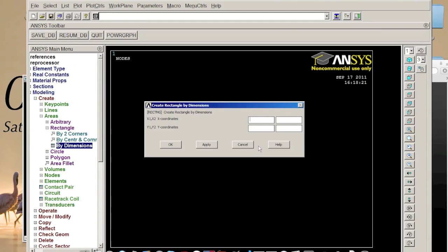And we want to do it by dimension. So I want to start with 0, and because it's about 5 meters apart, I want, for example, to put 100 here, so it will be far enough to represent the infinite soil. Okay, for y, it's 30 meters deep, but I want to use it starting from 0 to minus 30. Oh, it's going down. Okay, just click OK.